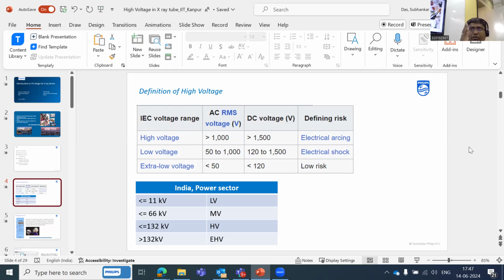On the high voltage tank, again, one of the major failures is high voltage instability, but the high voltage tank has a much higher life, 3 times, 4 times, meaning 20 years, 25 years. And in case the high voltage tank is diagnosed by the service engineer as having something happening related to high voltage instability, no repair work is done at site, it's done in the factory.